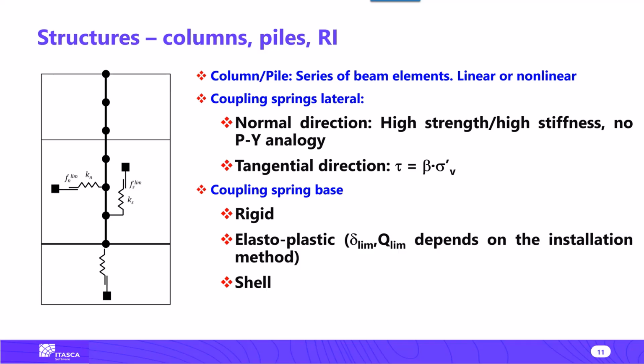In the vertical direction, the concept is a little bit different. In this case, we can see those vertical sliders as similar to the T-z curve, because typically the vertical movement happens in a very thin layer of soil. And in order to capture the interaction at that scale, it would require a mesh density that is most of the time not compatible with a large project.